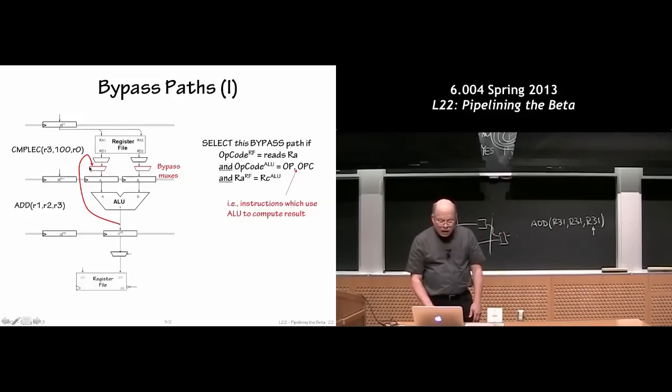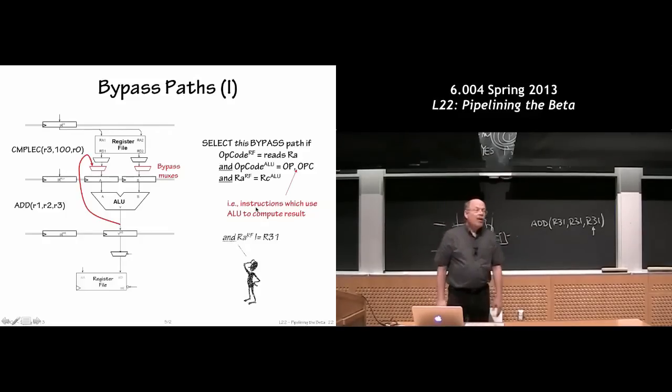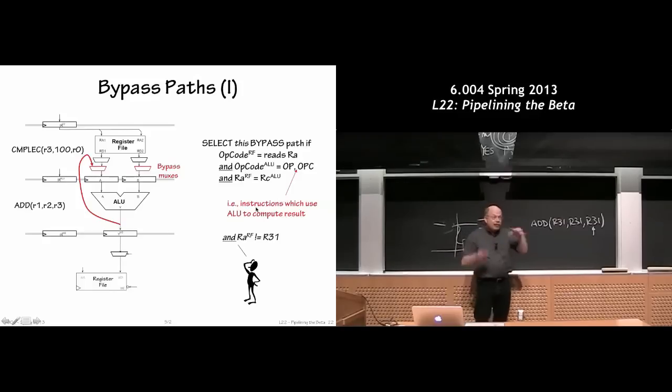Implementing all this logic sets the control line, the select line for that multiplexer, based on all these conditions. You can write logic that computes all of these: is this binary number equal to that binary number, and so forth and so on. You can do that, but this logic starts piling up.